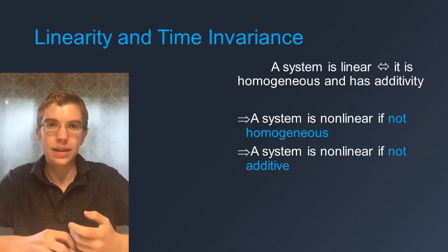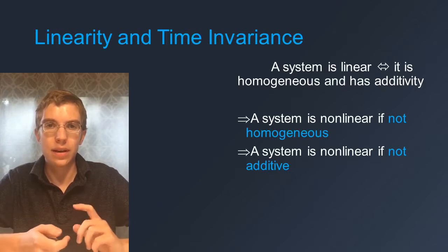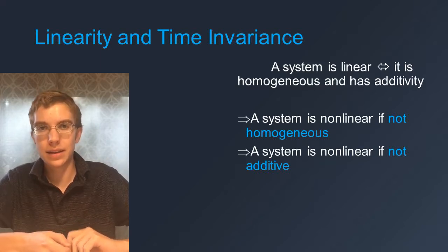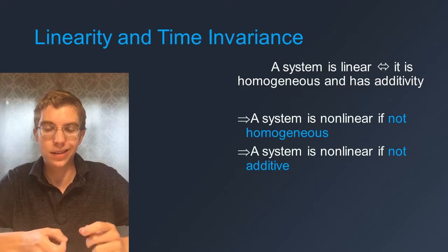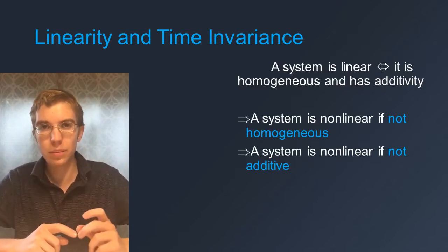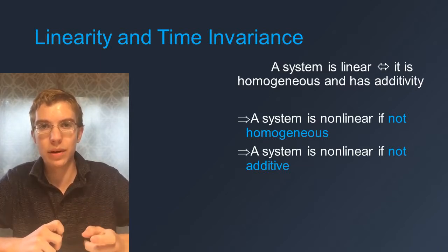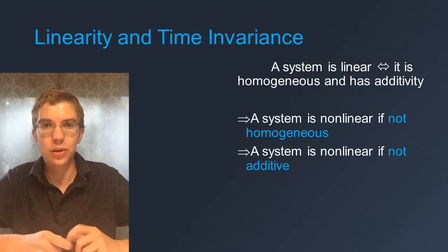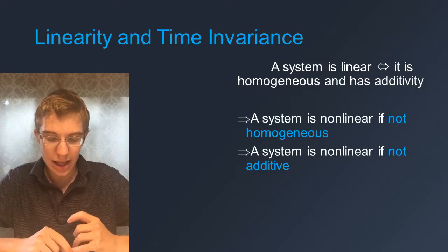And again, for time invariance, we can see this just through observation. None of the circuit components are changing with time, and a delay in the input of the signal is going to produce an identical delay in the output of the RC circuit. So the point of the RC circuit here is to smooth the output of the rectifier. And this is done by the capacitor reducing the change in voltage over time of that output. We can see this